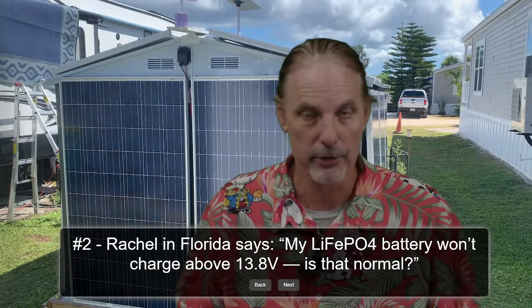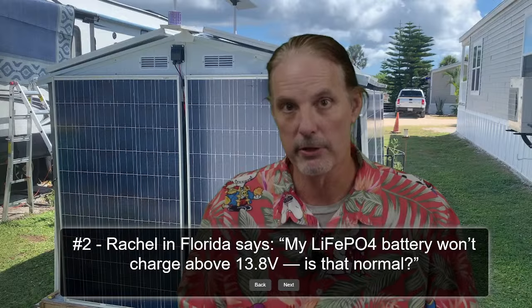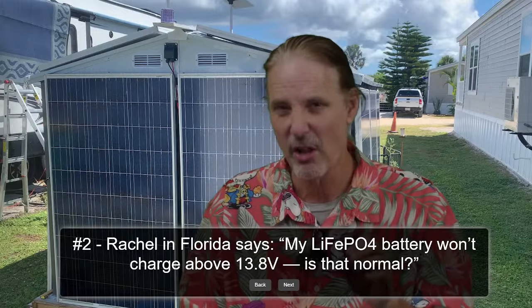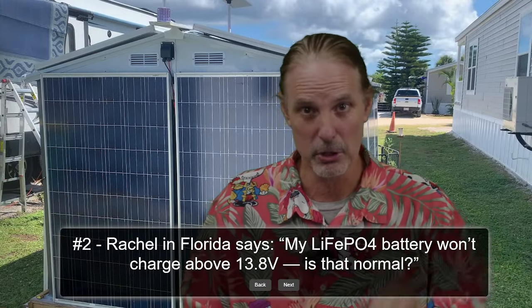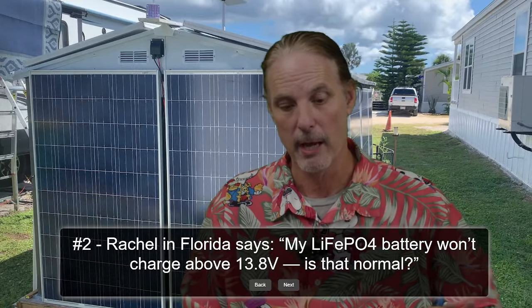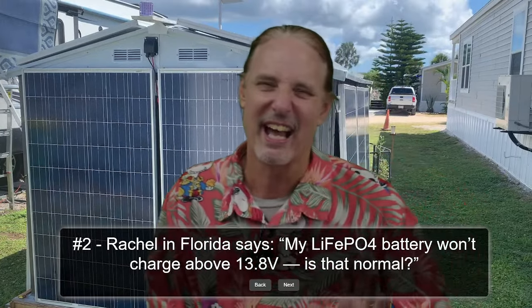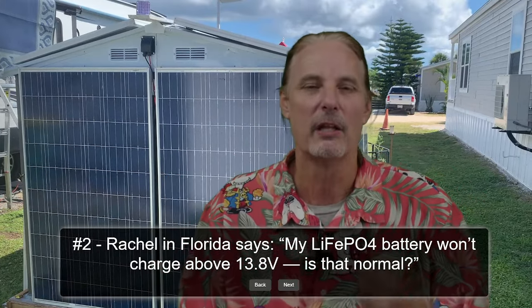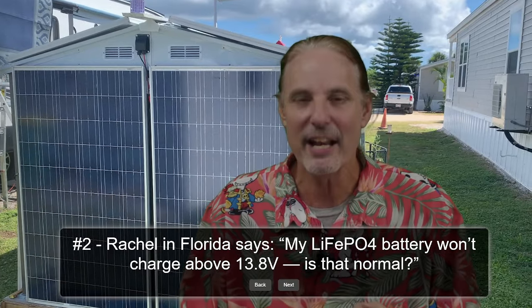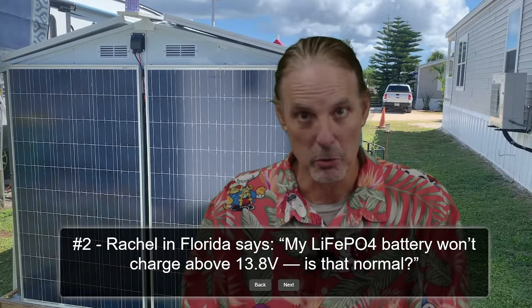They have no balancer, and they get out of balance, and there's basically nothing that can be done other than somebody manually hooking chargers up to each of the cells and fixing it. They also sell balancing devices that can be hooked up to those batteries. That is very much old school at this point. Most people don't use balancers of that nature, and I say that kind of tongue in cheek. A lot of people still use it. A lot of people still do it. A lot of those batteries still exist. I don't do it because I make sure that my BMS is doing that for me.